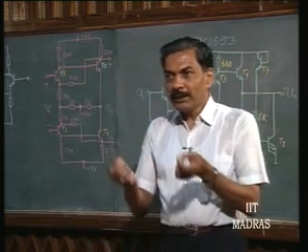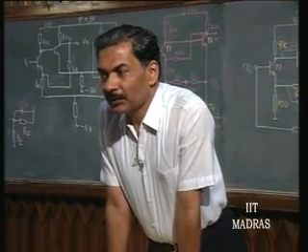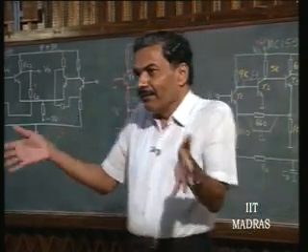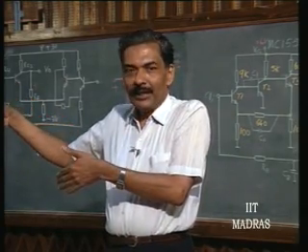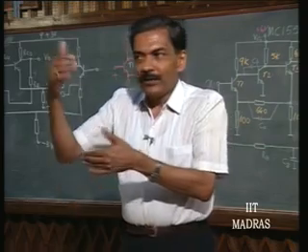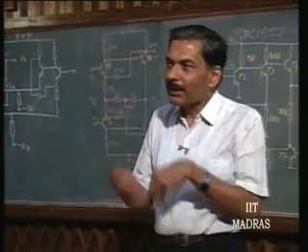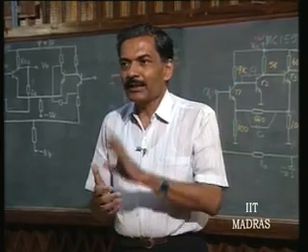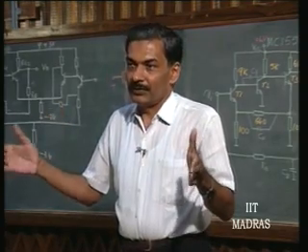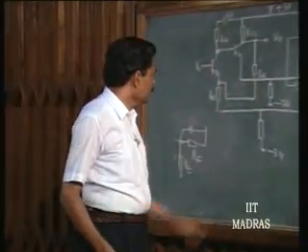Okay. So, this is what is provided externally by you, and the IC manufacturer will not give this capacitor or even suggest it. So, what you normally do is you will put just the value of capacitor that is needed to prevent oscillation. So, one way of doing it practically is simply observe the output, okay, see whether it is going to oscillations at all conditions of supply voltage and temperature. Okay. If it is going into oscillation, then increase the value of capacitor just enough so that it is eliminated. Just put a little bit more than what is needed. Okay. So, this is a practical way of stabilizing this wideband amplifier and also obtaining the maximum possible bandwidth for your usage. Okay. So, this is the compensation that is normally adopted for this kind of configuration.